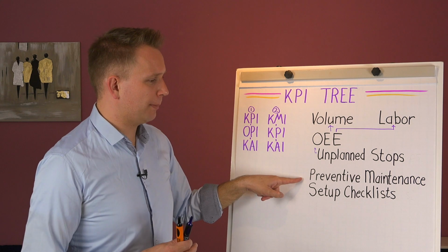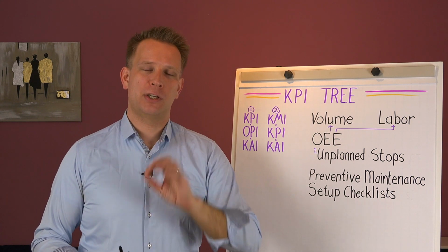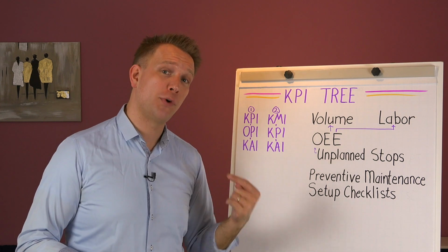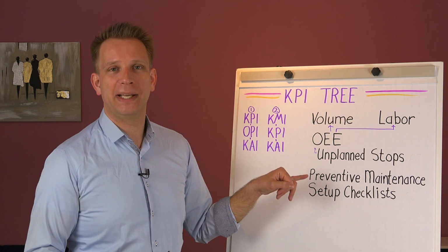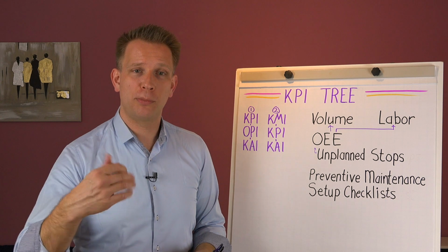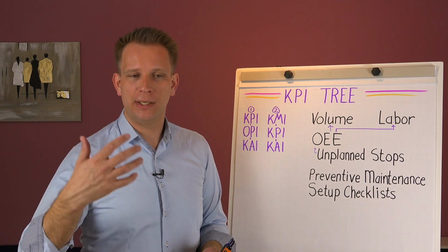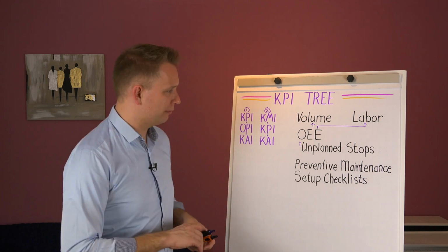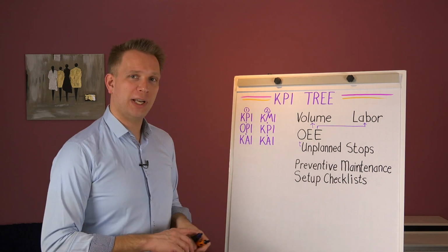Those ones. So we want them completed, but also that second category, the corrective maintenance orders, because they often come from inspections or preventive maintenance tasks, and they also come from all of the AM checks and all kinds of checks that the operators do. So if we have those two, then we can check preventive maintenance.